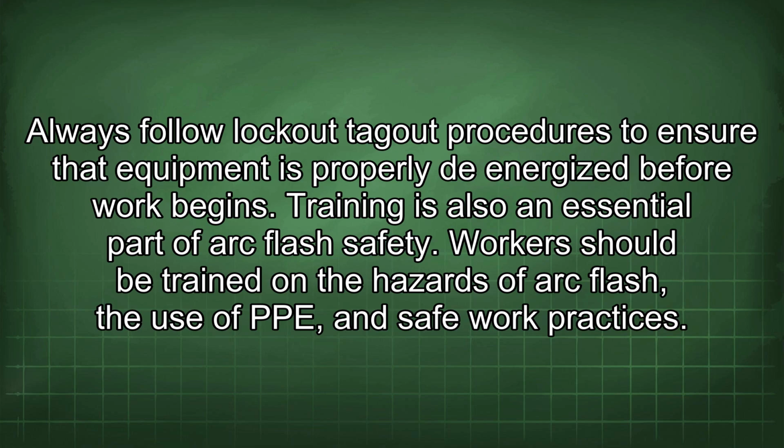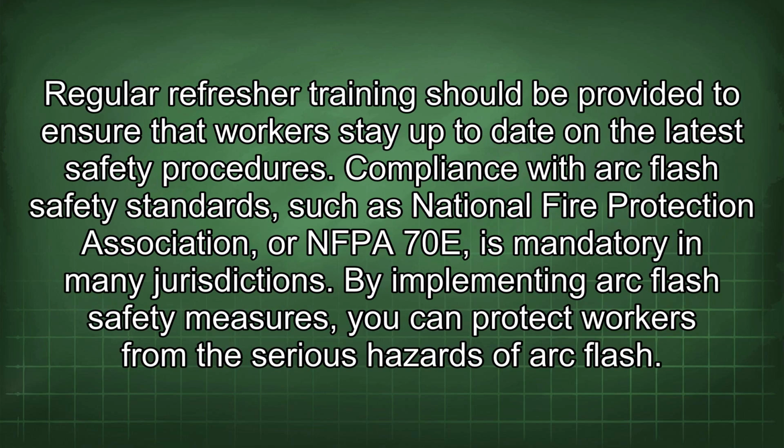Training is also an essential part of arc flash safety. Workers should be trained on the hazards of arc flash, the use of PPE, and safe work practices. Regular refresher training should be provided to ensure that workers stay up to date on the latest safety procedures. Compliance with arc flash safety standards such as National Fire Protection Association or NFPA 70E is mandatory in many jurisdictions. By implementing arc flash safety measures, you can protect workers from the serious hazards of arc flash.